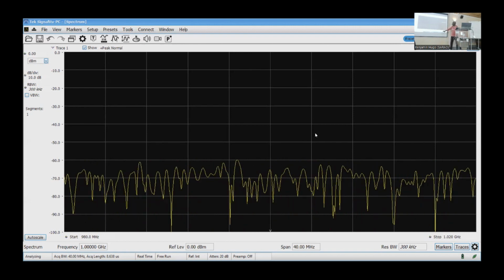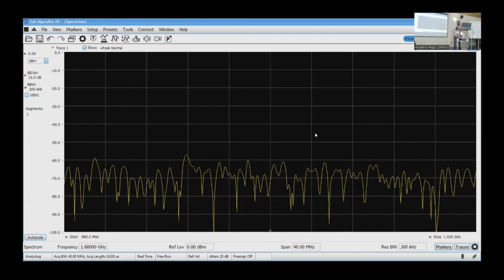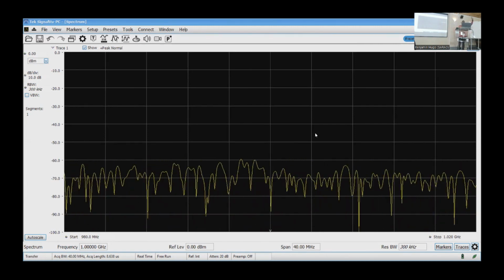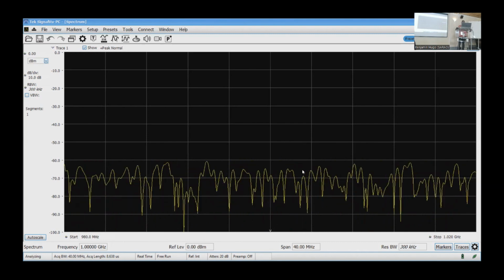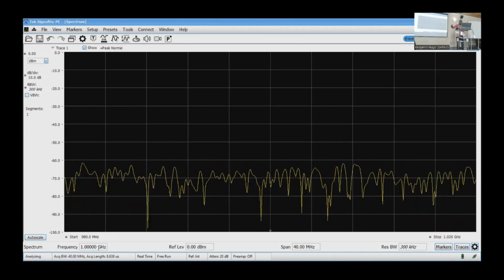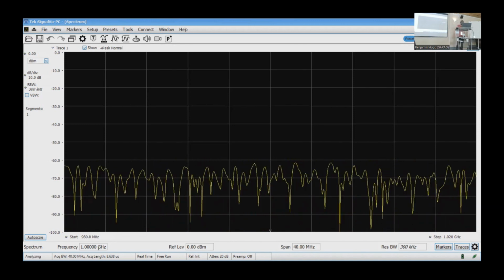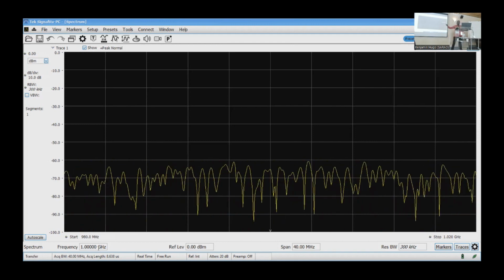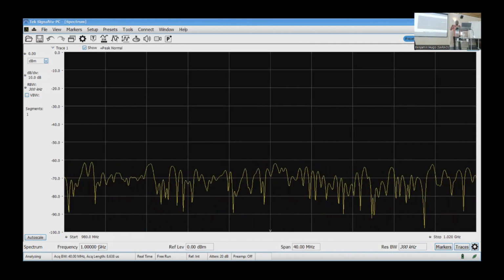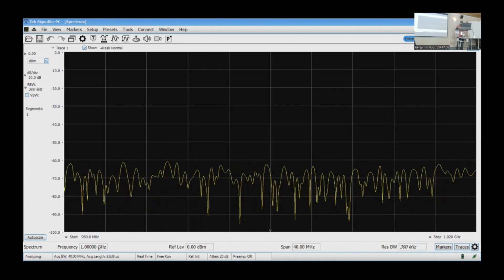Now, this is the normal spectrum. We see the normal spectrum analyzer, this window here. If you are not familiar with the spectrum analyzer, there are 4 things you need to look at. By the way, when you're doing measurements, you must know what you want to find. Don't just go in. First you must know the correct connection. Even this setup is probably not the best setup, I'll tell you from the EMC point of view. And then you must know what you are looking for so that you set the parameters right.